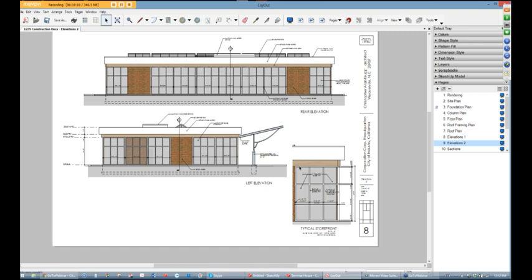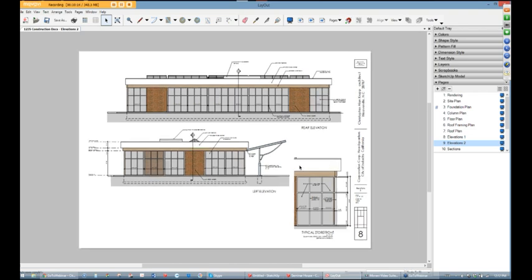Think of layout as basically the same as AutoCAD paper space, model space, because that's what you have. The model is kind of nice here. It's the model space, and the paper behind it is the paper space. The reality is these all have viewports.